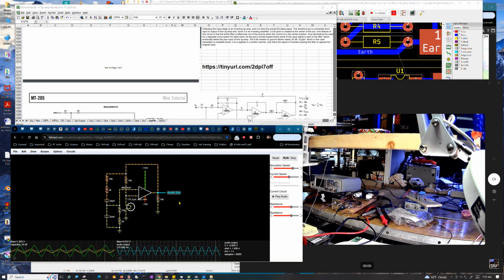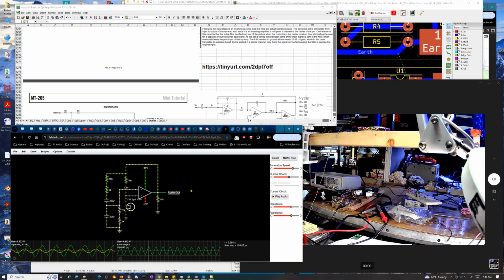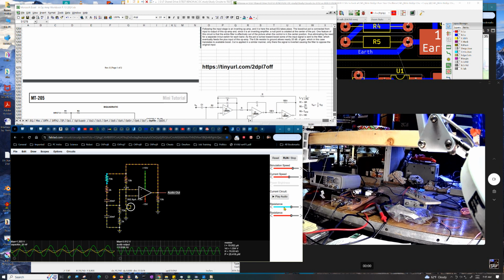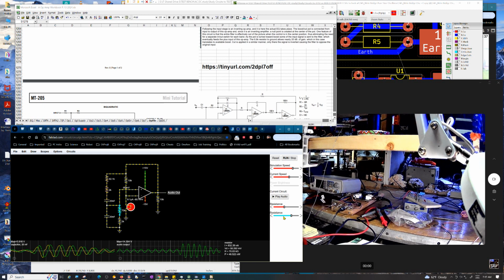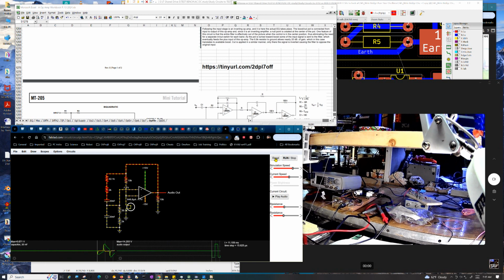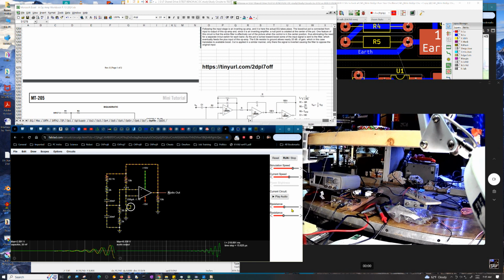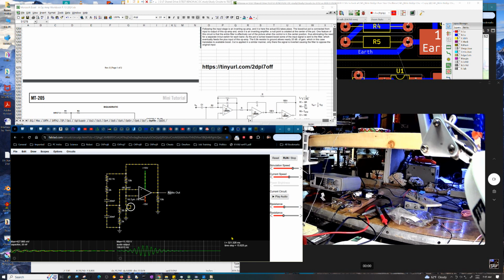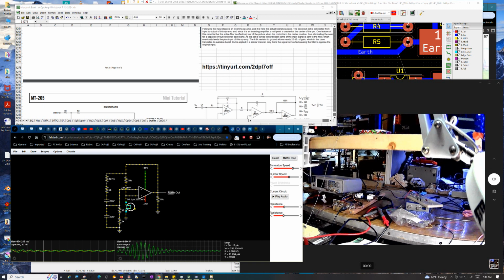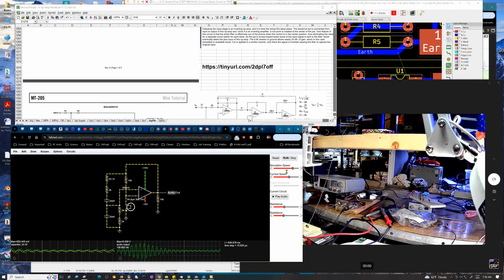But basically, that's a little oscillator for you, and it's a simulation in Falstad, and you can change the frequency by varying these resistors and so forth, but of course it'll probably die off. It's kind of tricky to get this thing to work. I was lucky. You've got to have the right resistance value, I guess. Now it just takes it a while to figure out where it's at. When you change the resistor, it'll change the amplitude, but this thing gets confused with the bulb. It's got to kind of figure out its sweet spot every time you change it, so it takes a while to stabilize.